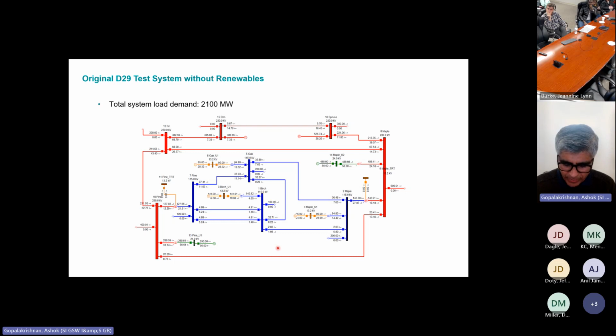On a transmission line, you have line protection, and if you have a line fault, that line protection is primary. In that case, the local bus bar protection is a local backup, whereas another relay at another substation becomes a remote backup. Traditionally in this kind of analysis, we're measuring the interval between your local relay and your remote backup relay.